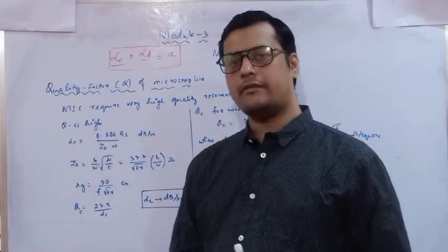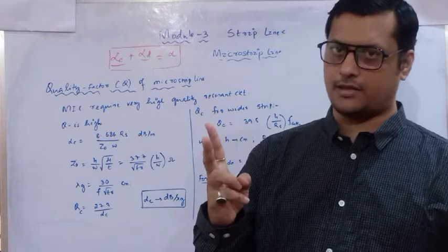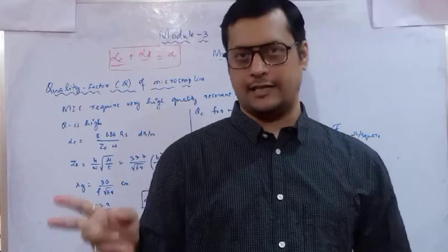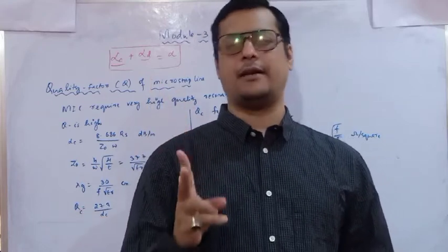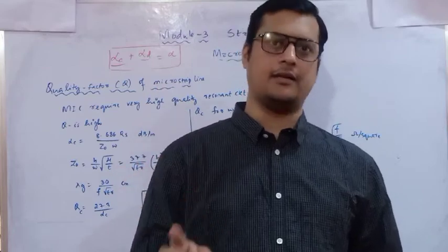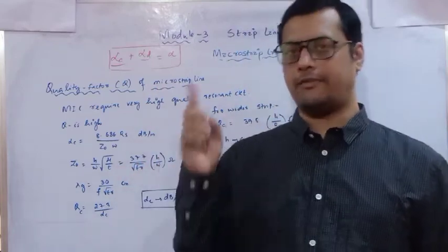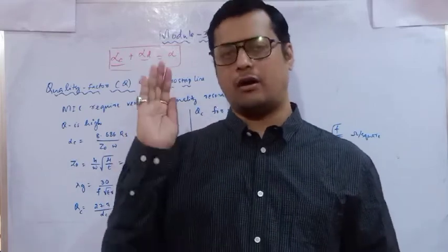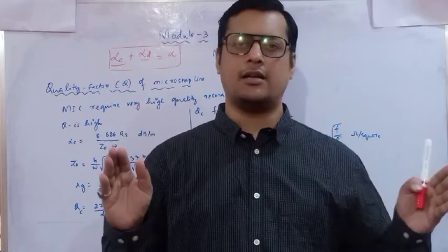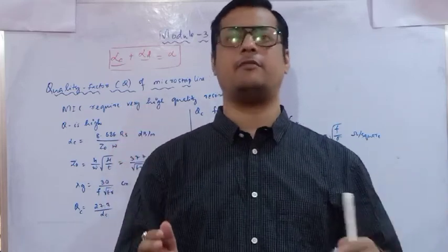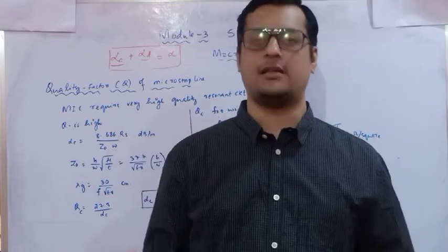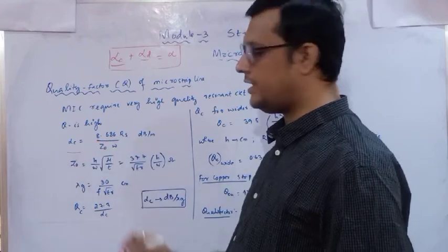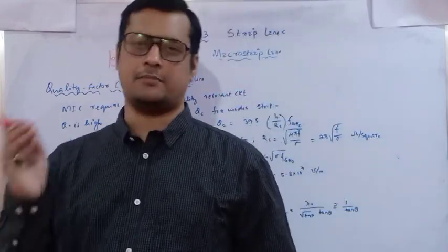So now when we are dealing with the microstrip line, we have two attenuation constants. One with respect to conductor and one with respect to dielectric value. Always remember that your quality factor depends upon this attenuation factor. Quality factor will be high when the attenuation factor is less. Quality factor will be low when the attenuation factor is high. So we have to always minimize the attenuation so that the circuit can properly work in a resonating condition for a higher measurable output. So for the conductor, I have started with alpha c, and then we will discuss how it is related to the quality factor.